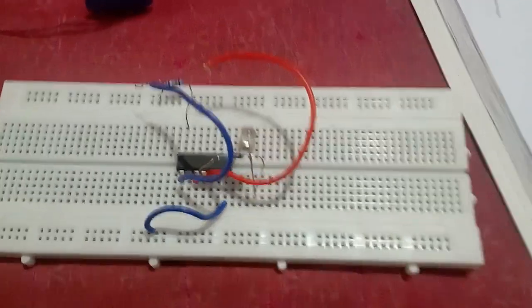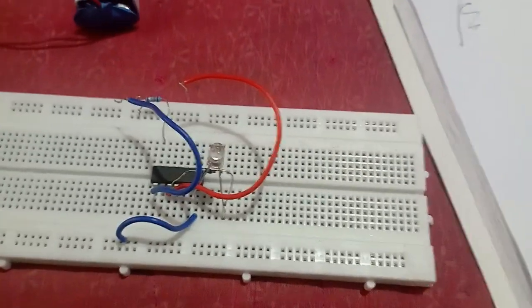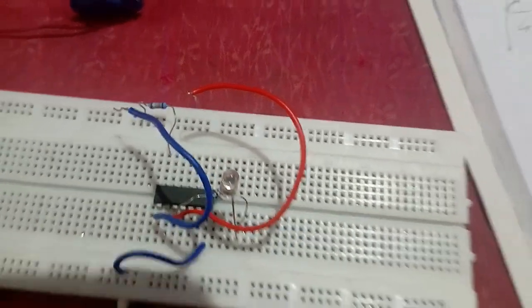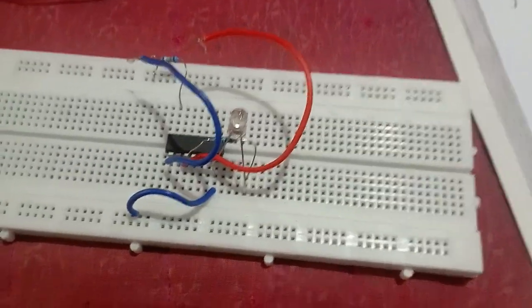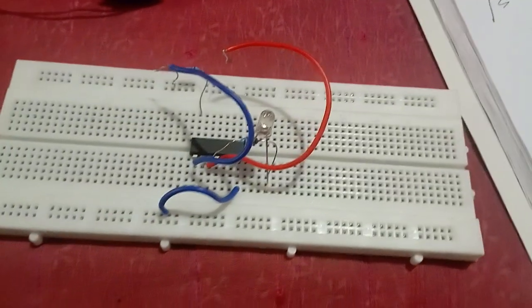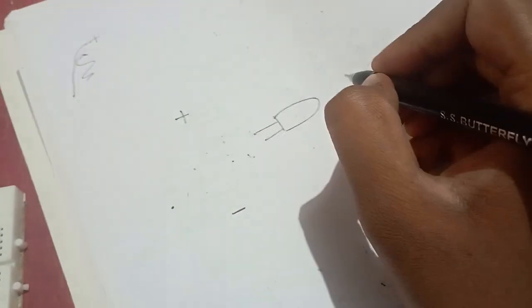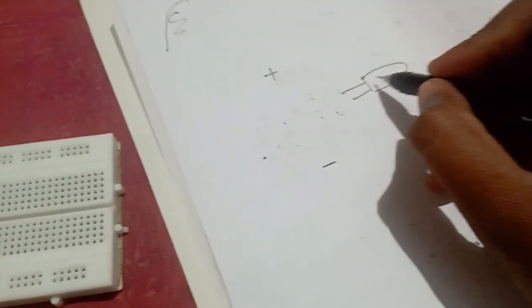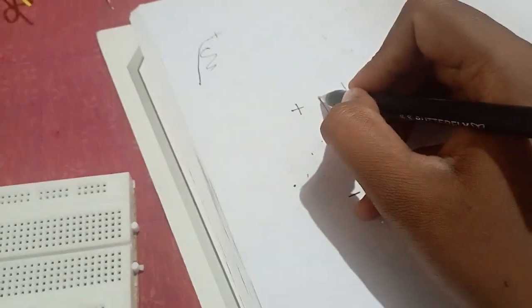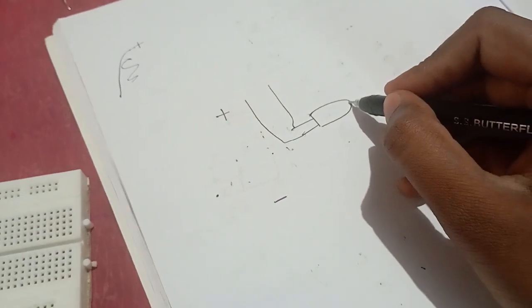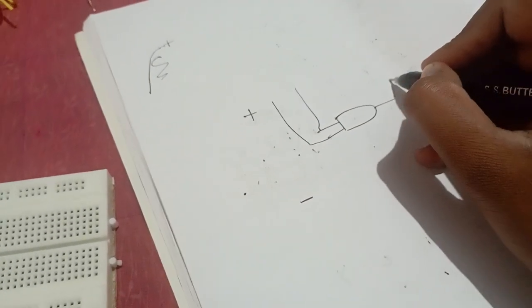So I am going to connect an IC, the 14th pin for the positive end and the 7th pin for the negative end. There is an AND gate inside the IC. That is this gate. So this is an AND gate. For the AND gate I am going to leave two open wires. So these are the two open wires, and for output I am going to connect one.